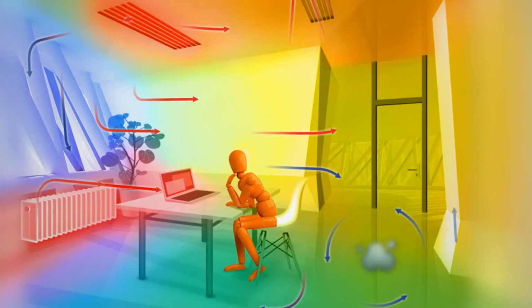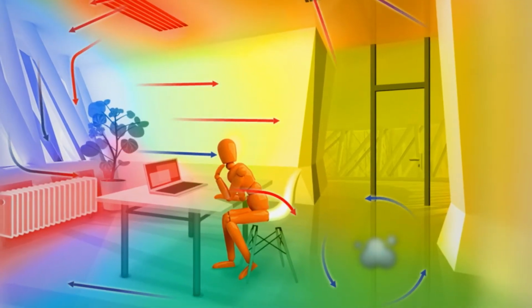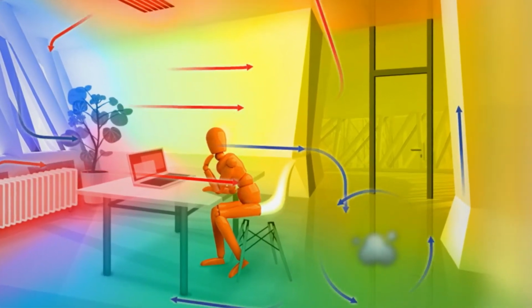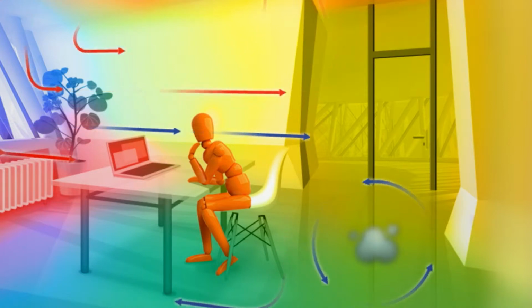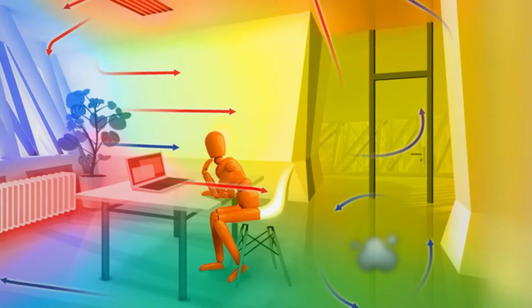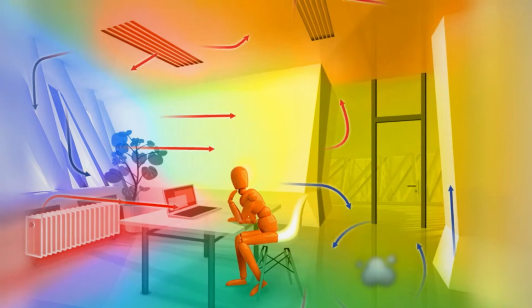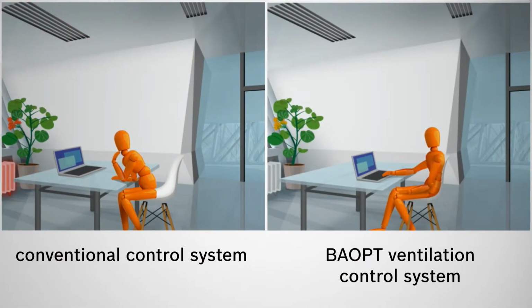in the room does not mix in the most effective way. This results in pockets of temperature and pollutants, which can have high levels of CO2 and cause temperature stratification. These systems can also cause unpleasant drafts. Cold descending air or warm ascending air on glass surfaces and exterior walls increase energy requirements.